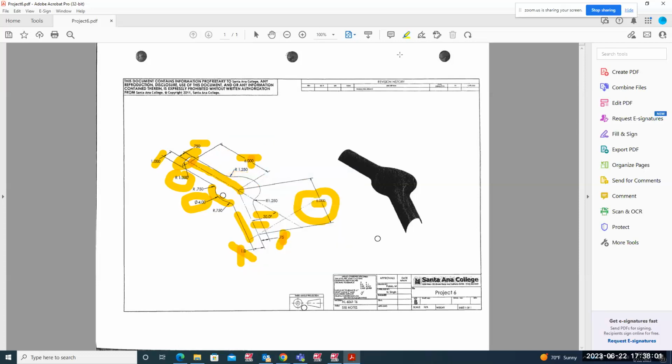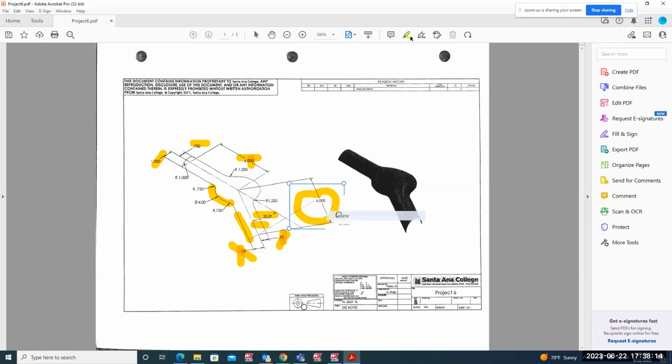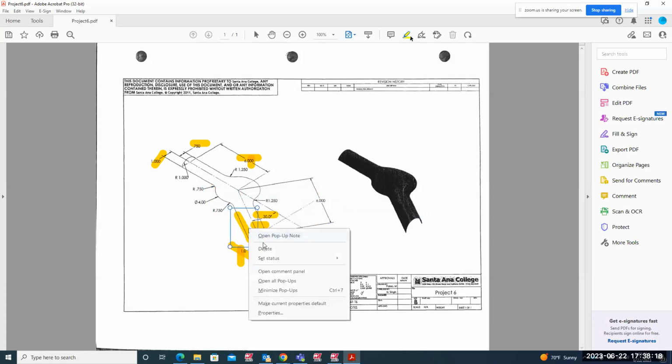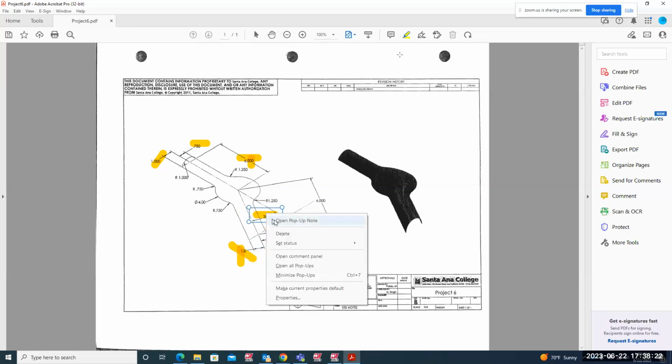So this is what we're going to do. We're going to start with the construction plane top at Z0 and create those lines, then offset those lines, and create arc polars, 2 arc polar with diameter 4 inches or radius 2 inches, doesn't matter.